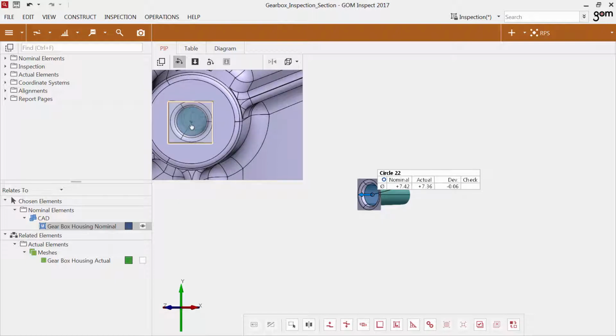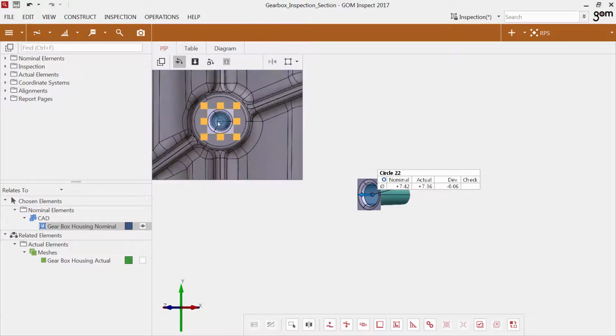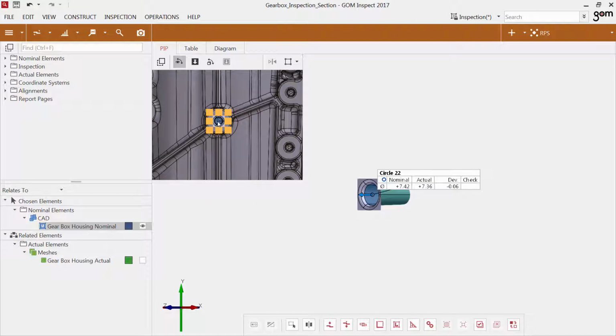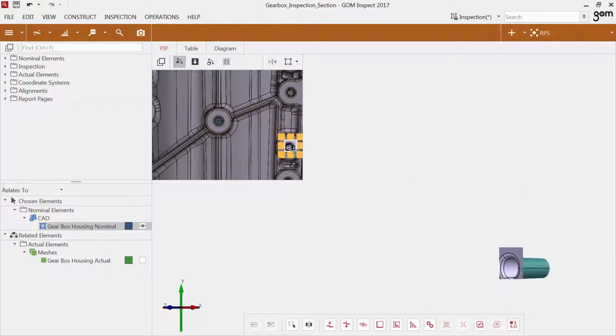After inspecting this area, I can use the clipping block for another area of interest. I just hover the mouse over the clipping rectangle until the move cursor appears. Then I drag the rectangle to another area which has a similar size. I can still edit the clipping block afterwards. Using clipping, it is easier to inspect small hidden areas of a big measuring object.